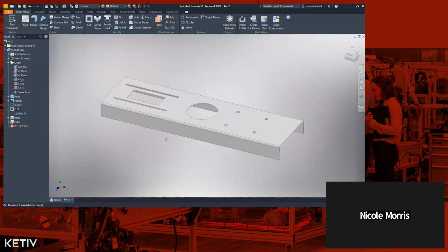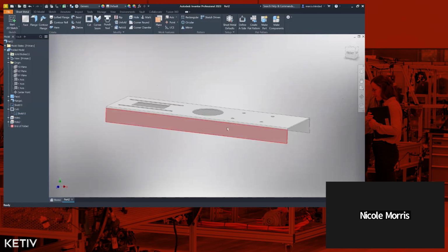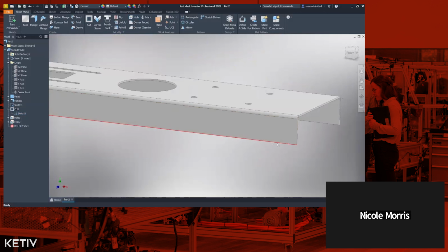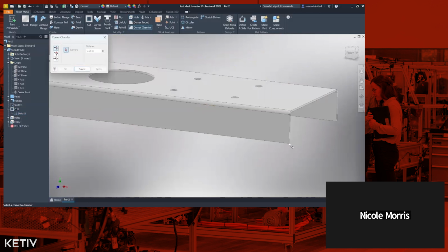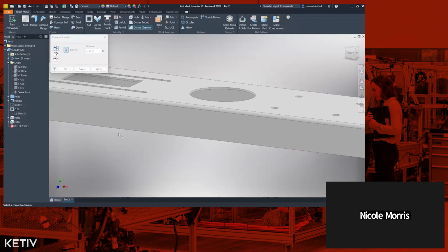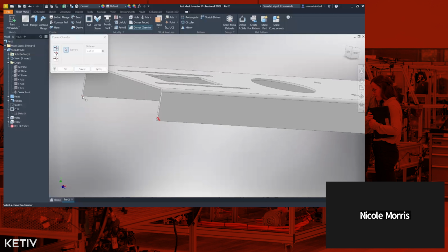So next up, I want to create my cutouts on the side. So there are some slits on each side, but they are symmetric, so I only need to create one. But I do see that one of the dimensions is based off of a chamfer it has on the edges, so the next thing I'll do is actually to chamfer here. Go in here, select my 4 edges, and that's going to be 1.8.